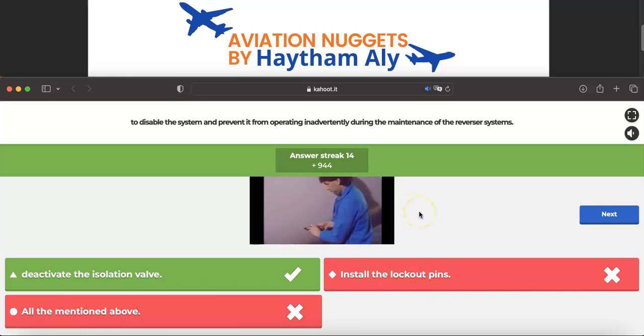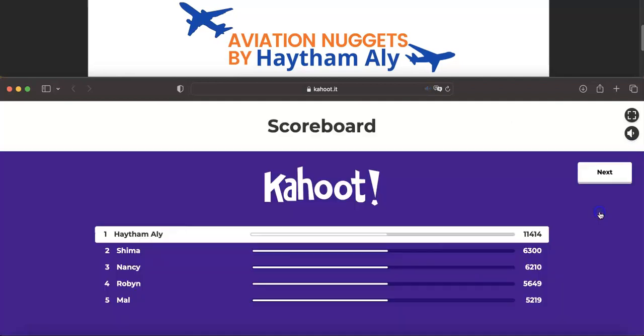If the aircraft will fly, we cannot only do the hydraulic deactivation, but we always need to do the mechanical deactivation. Insert a pin so that the translating sleeve will be locked with the engine case, and also a mechanical deactivation happens. So what you are seeing now is a mechanical deactivation. Okay, everybody, let's proceed to the next question.